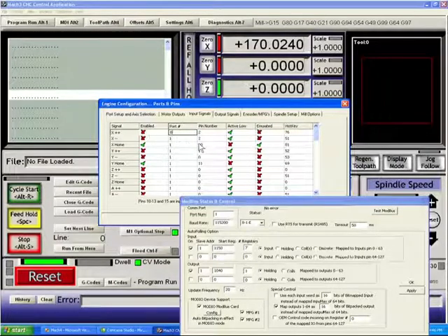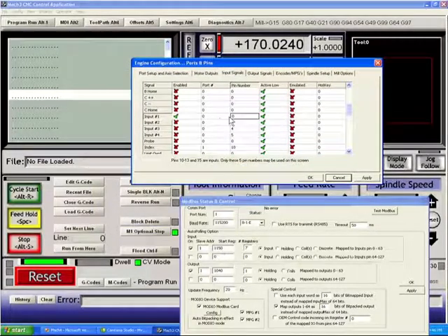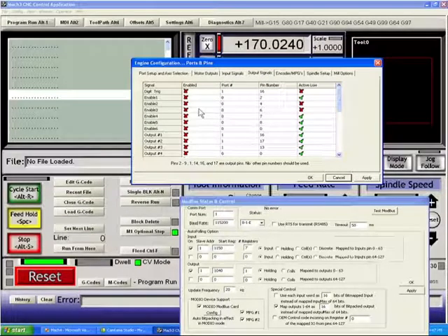So for example, if I was going to use a Mod.io board input as input number 1, I would turn it on, set it to port 0, pin 0. Active low is used the exact same way as any other input from the printer port. So the only difference between a pin here and a pin on the printer port is that port 0 means ModBus. Port 1 or port 2 are printer ports. Another nice thing about Mod.ios is you can use up to 63 pin numbers for your inputs, and at the exact same time, outputs are analogous to this. If you wanted to send an enable signal out, you could turn it on, set it to port 0, pin 0 as well.